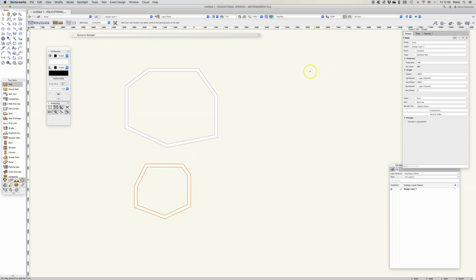If I use the left control line mode, I can define the internal dimensions on it. You can see if I go anti-clockwise, I'm doing the internal dimensions. So there isn't a right and wrong way, you just need to be aware of which way you're drawing, clockwise or anti-clockwise, whatever is natural for you, and make sure that the right or the left control line mode is on.